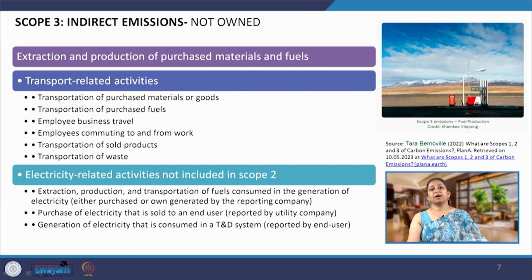For example, if I have to make a wall, I have the option of making the blocks as CSEB, compressed and stabilized earth blocks, which require no firing, no fuel, and a very minimal amount of stabilizer, which might be cement, and the clay, the mud, is procured from the site itself. Now compare the emissions associated with the CSEB with an autoclaved aerated concrete block, the AAC block, which is completely made out of cement.